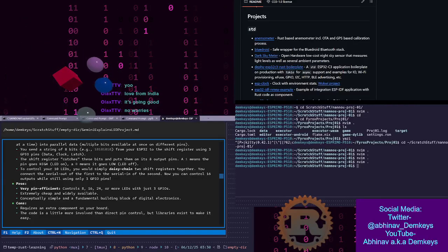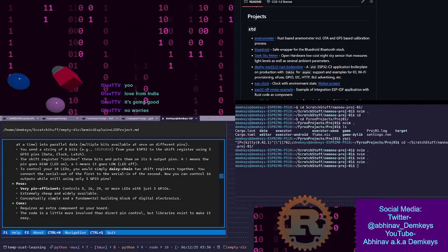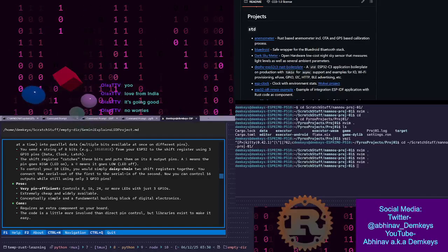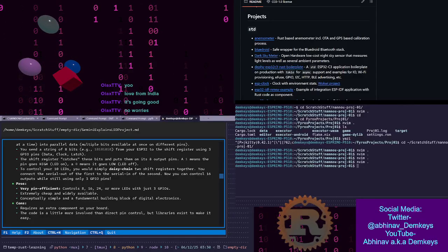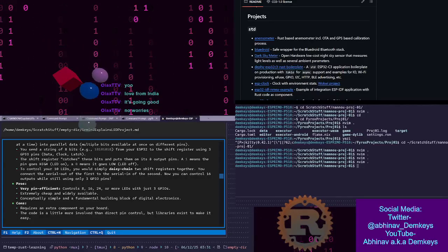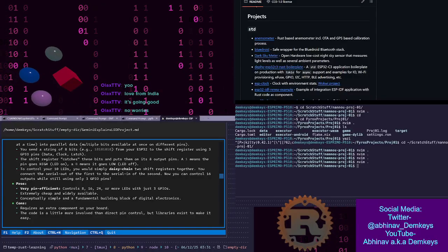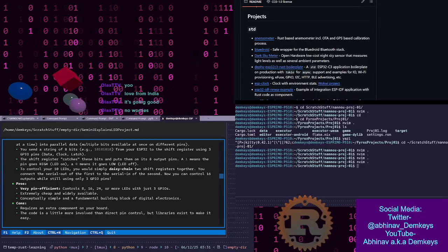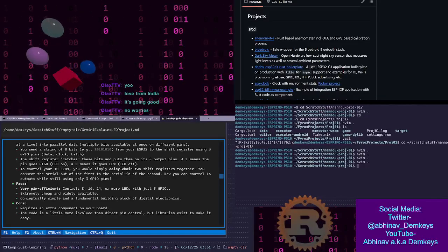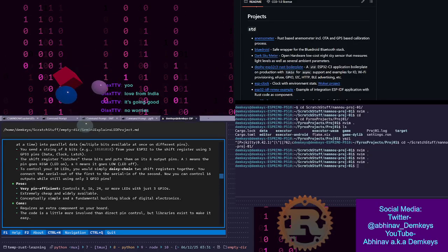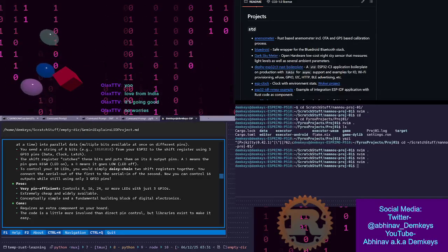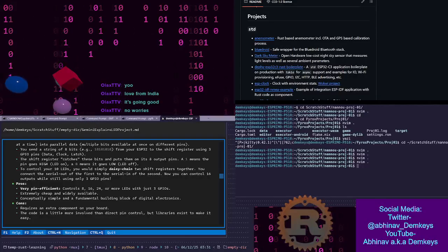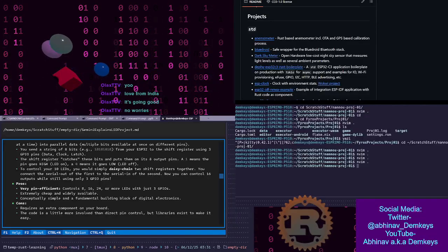Also, how do I know that it can put out enough voltage slash current to power an LED? When I'm buying these things, I'm assuming I'm gonna need to look at the rating, the voltage and current rating.